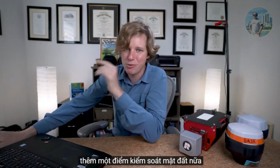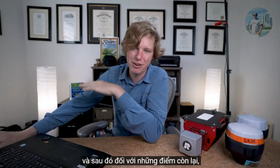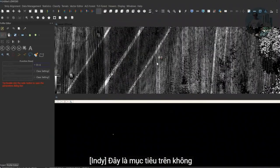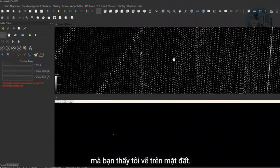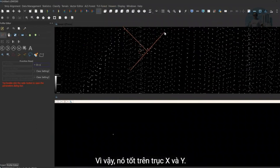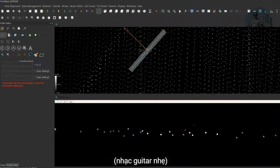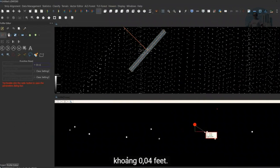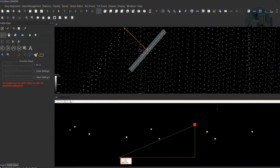Let's go ahead and take a look at one more ground control point, and then for the rest of them, I'm going to go ahead and just calculate them all off the video. Here's the aerial target that you saw me paint on the ground. And again, the point is basically right in the center, so it's good on the X and Y axis. Let's look at the Z axis. All right, the closest neighbor here is about 0.04 feet away. Now, 0.04 feet is 1.2 centimeters.